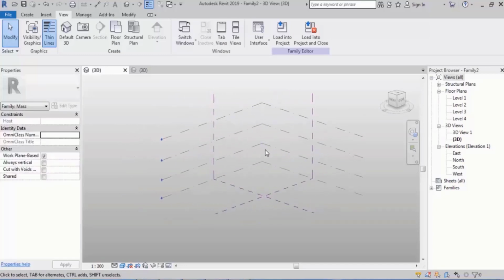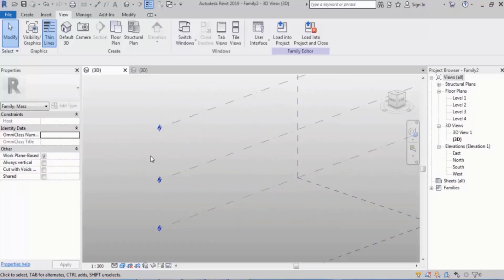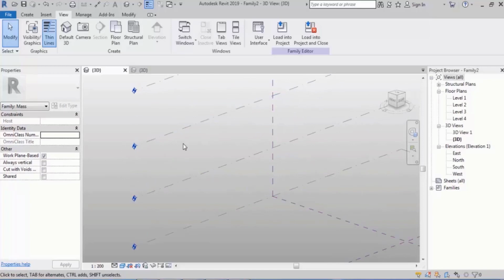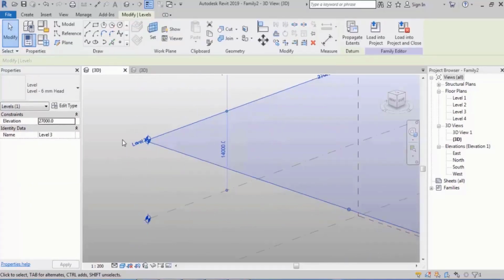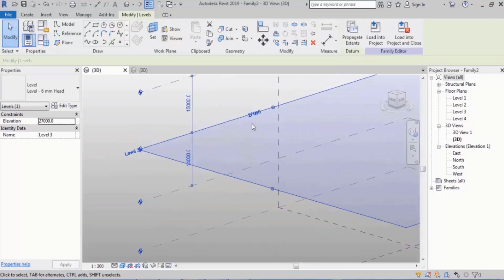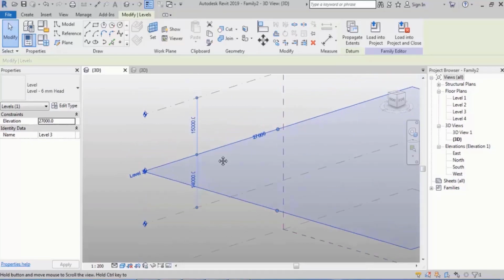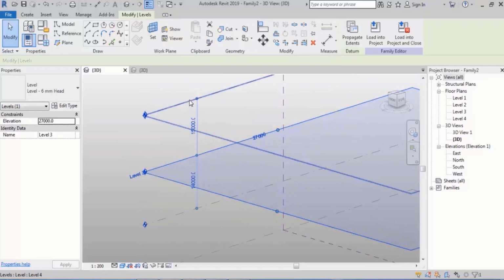Well, for managing the height of the level lines, what should we do? Each of the level lines you select, first of all, you see the name, and here you got a number, which is the height code of this level. I mean, the distance from 0, 0.